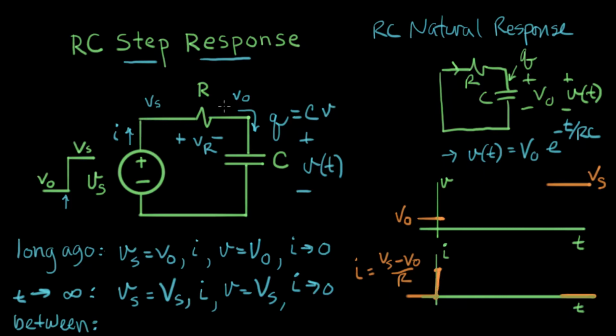And now there's more charge flowing onto our capacitor. So the capacitor voltage is going to start changing. More charge, more voltage. And we can estimate this, it's going to just do something like that. I can sketch that in. More and more charge will start flowing onto this capacitor, and the voltage will gradually rise until V equals Vs, till the voltage across the resistor, again, is 0, and then the current will stop. We had a sudden step of current caused by the change in the step voltage input, and then it's going to just fade out, something like that, until the current goes back to 0.